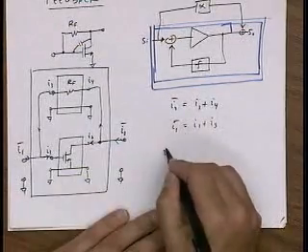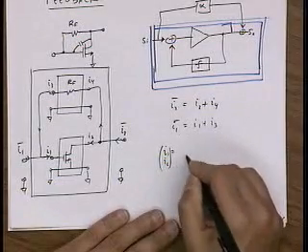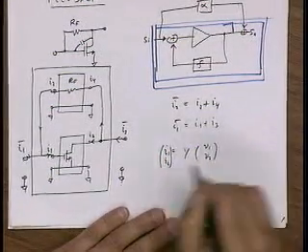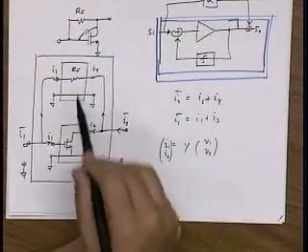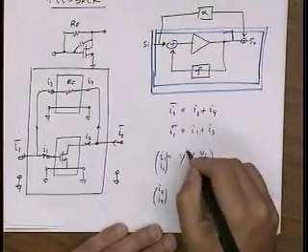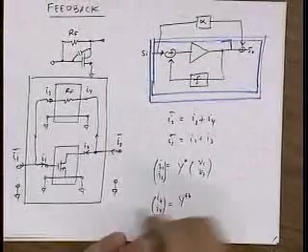So what I'd like to do is represent I1, I2 in this form, because on the right hand side the voltages are the same for both two-ports. So I can also write I3, I4, let's call this YA for amplifier, and YFB for feedback.